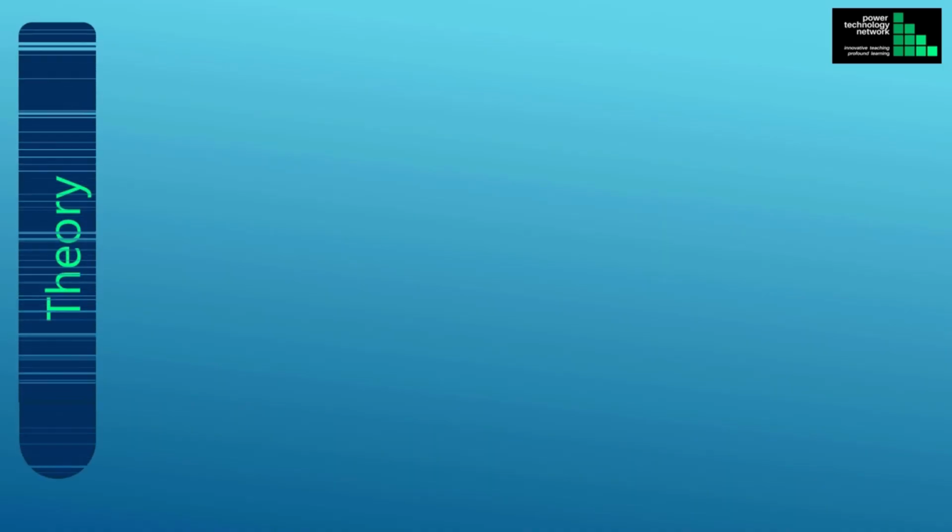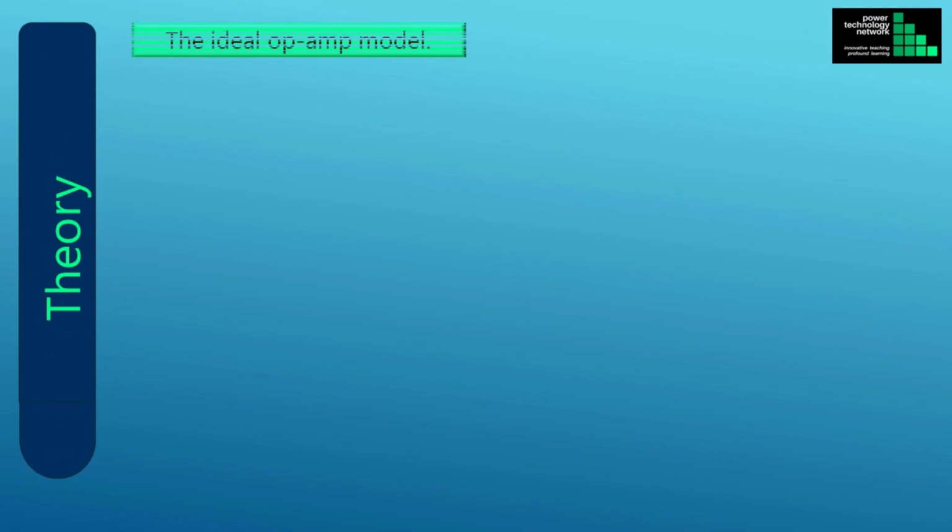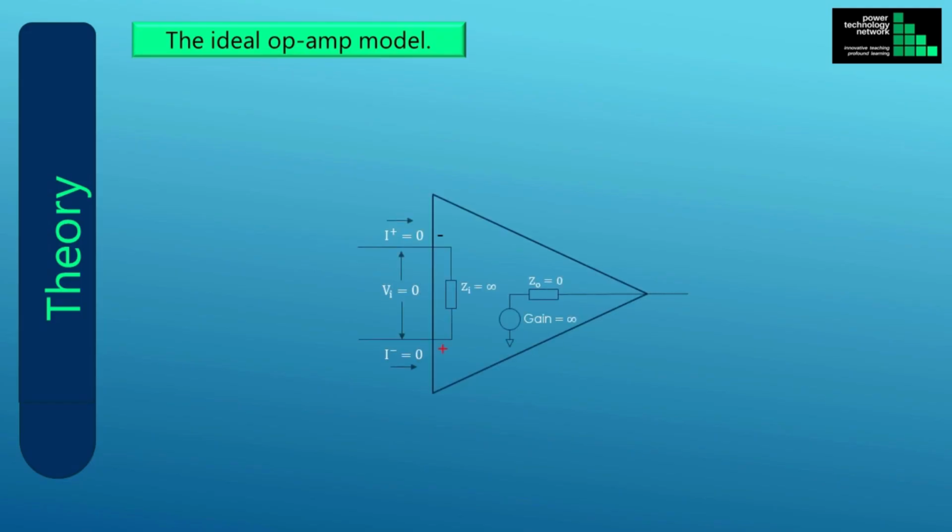We start with the schematic for the ideal op-amp. And this is the schematic for the ideal op-amp. It is a relatively simple circuit. And we shall delve into it in more detail in this section. It forms the basis for the rest of the development of a more complete behavioral model. Note that this model has a differential input, meaning that the input signal is the difference between the two input terminals. And it has a single-ended output, meaning that the output signal is measured between the output terminal and ground.